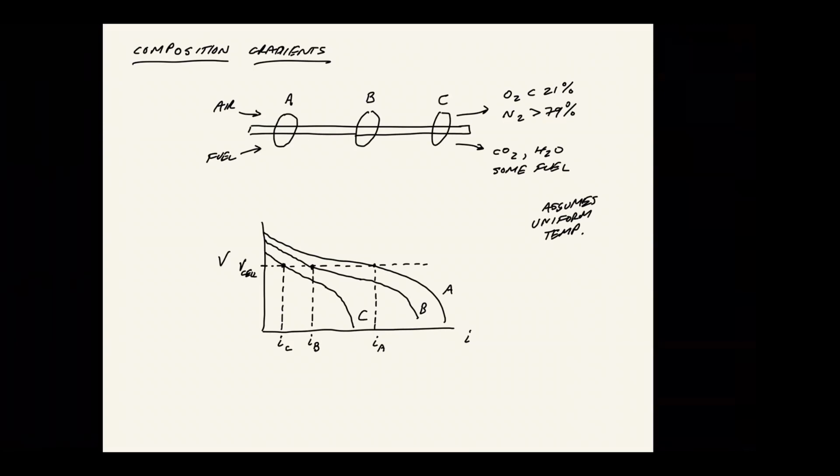Like, we have the bulk transport, convective, and then there's a diffusional boundary layer. And so as we get farther and farther along, there's less of a driving force because the delta between the concentrations is decreasing, or there are two different effects. There are two different effects, but they both affect the polarization curve.